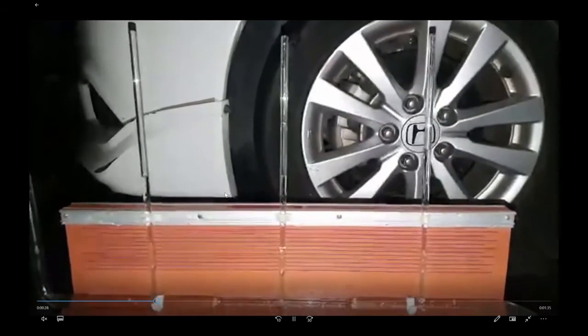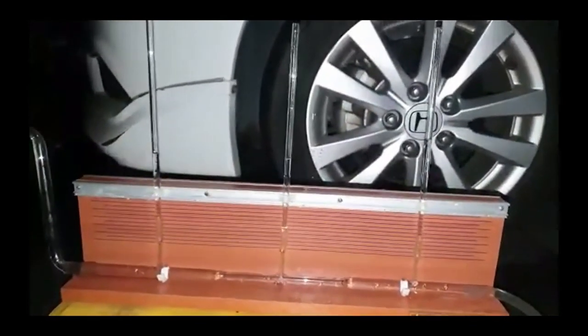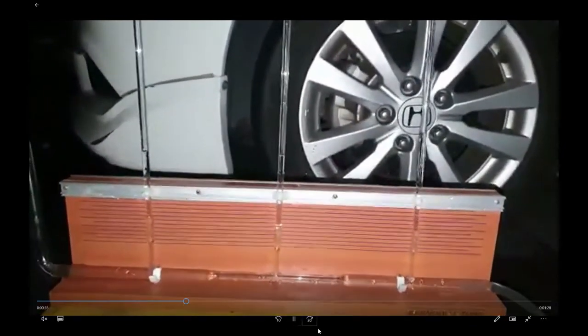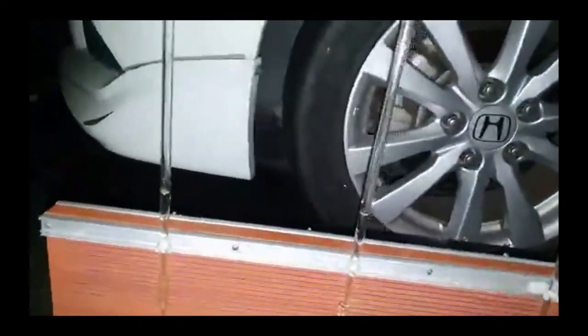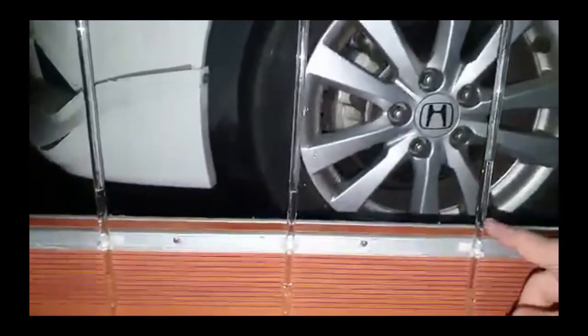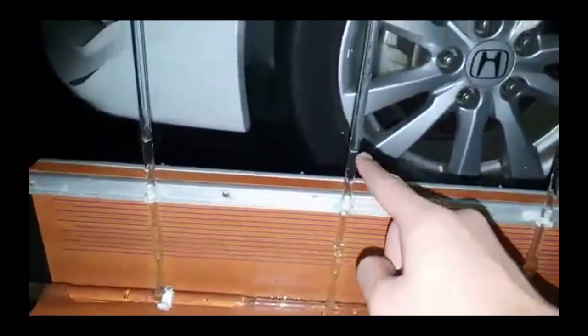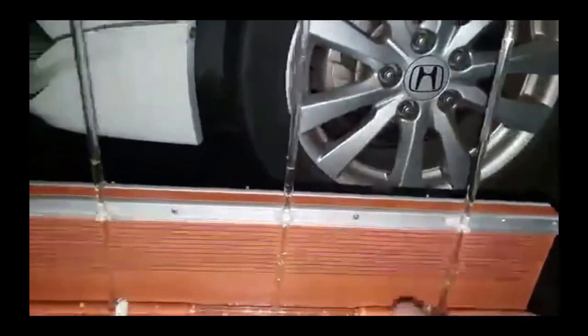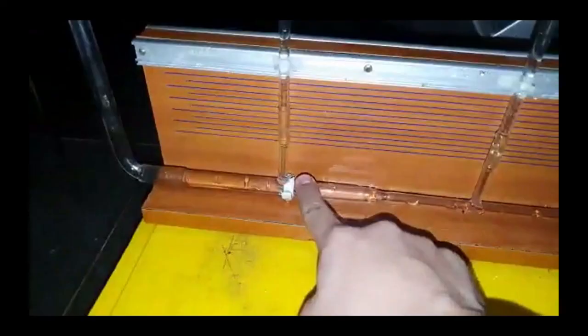As the fluid flows through the pipe, it goes through the convergent part, the throat, and the divergent part. The convergent part is where the area of the pipe becomes smaller. This is where velocity increases and pressure decreases. Then the throat, which is the maximum velocity point. Lastly, the divergent part is where the cross-section area expands, where velocity starts to decrease.